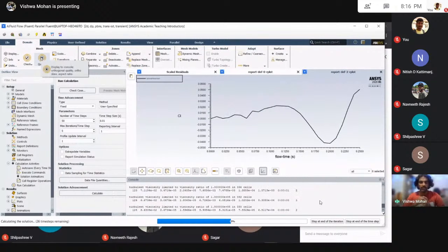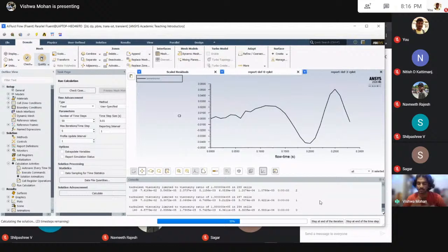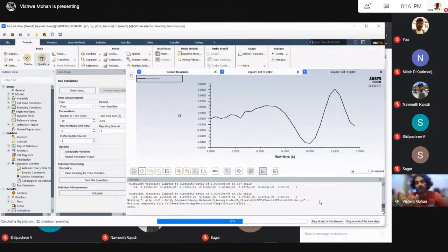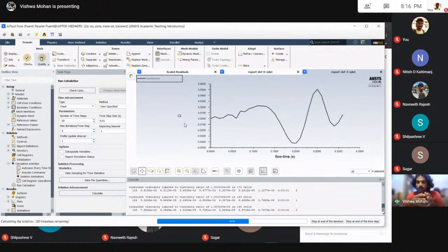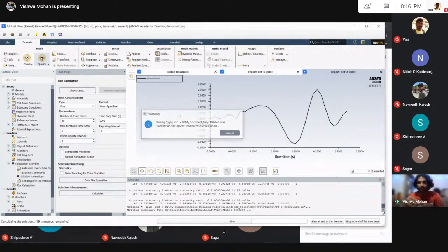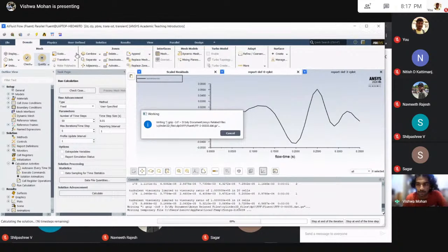That's in the software. But talking in theory about the mesh and everything, it's a whole domain of study. Basically, you need to check the skewness and check that the mesh is not too small. There's this number, the Courant number, I'm just completely missing that number, but it should be less than 1 if you want a good simulation. If this is your domain and the fluid flows through the domain before even one time step has happened, you'd miss a lot of stuff. Mesh sizing and everything need to be taken care of. And as you can see, we are getting very weird curves over here.